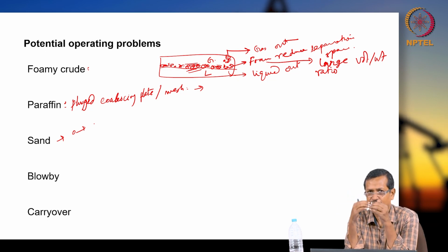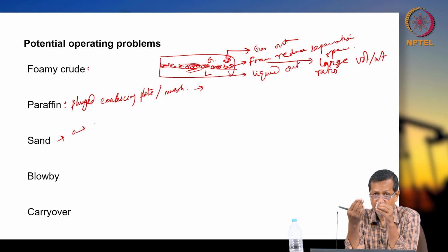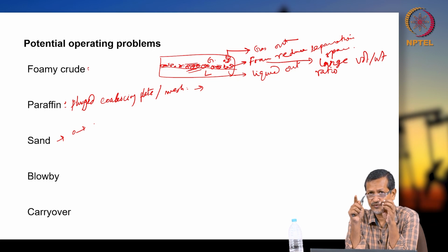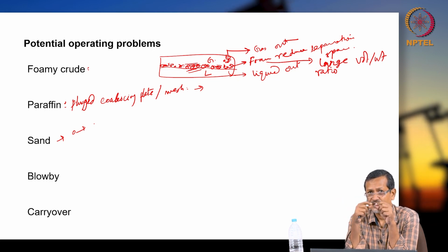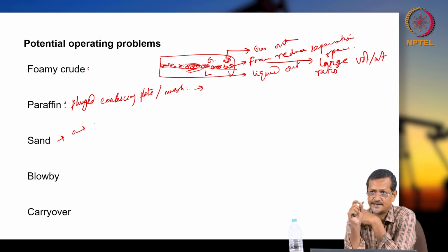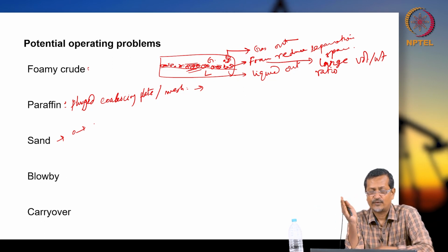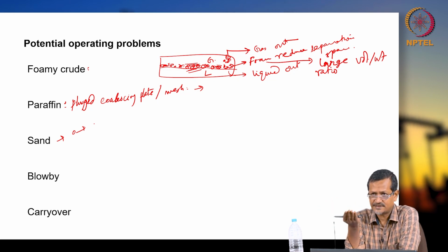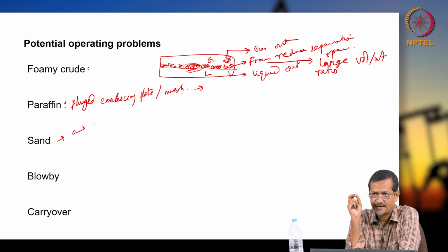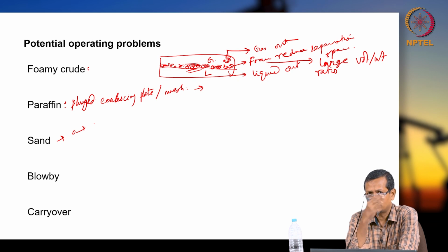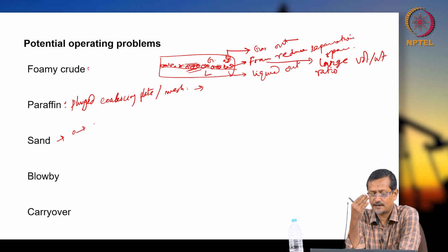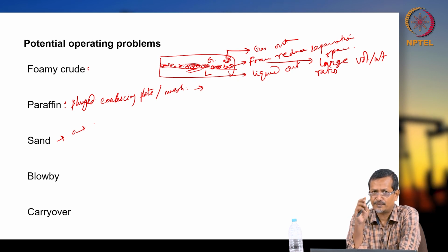Corrosion needs a fresh metal surface and corrosive gas. It will react and create salt, let us say iron plus H2SO4 giving iron sulfate, which is a softer material, and sand is there. So sand will remove the iron sulfate. When sand removes iron sulfate, a fresh metal surface comes up again, the acidic gas reacts on the metal surface, creates salt, and sand removes that. So continuously this erosion and corrosion will be occurring, and your metal surface will be eroded.